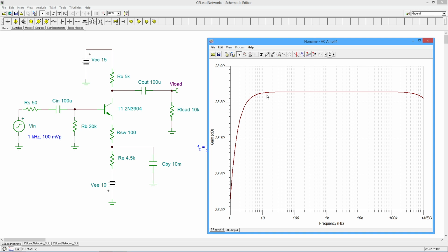Now, because voltage and power are related through a square, right? Power is equal to voltage squared divided by resistance. To get that factor of 2, you don't need a factor of 2 in voltage. A factor of 2 in voltage, that's 2 squared, which is a factor of 4 in power. So in fact, you only need a square root of 2 for the voltage change.